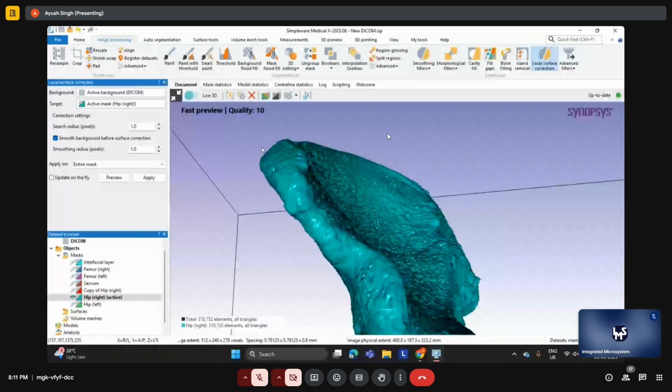And generally a value around 1 to 2 is recommended for the smoothing radius, as the higher the value, it might distort the particular workspace that we are working on. So taking a default value of 1 and 1, I'll just click on apply, and let us see how the resultant changes look. After every operation, our mask gets out of date, so we need to click on generate a fast preview, and we can see it has done a pretty decent job while marking up the region. We can also check out the surface correction over here. It has marked up the boundaries very clearly.